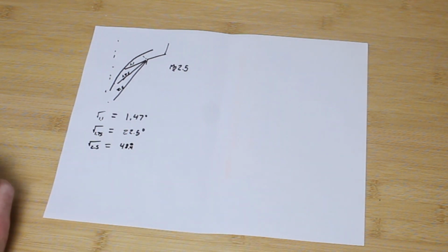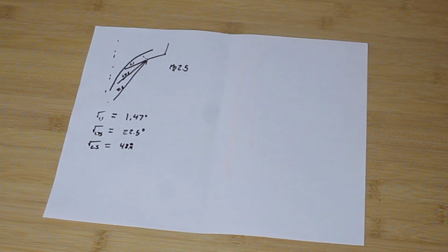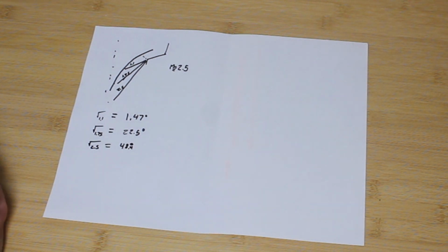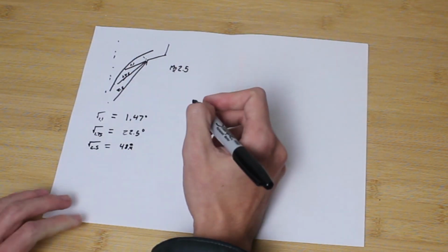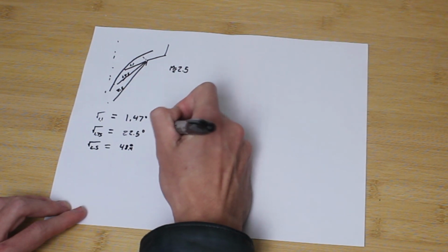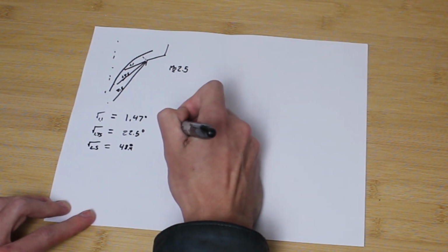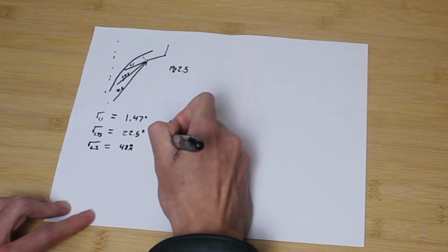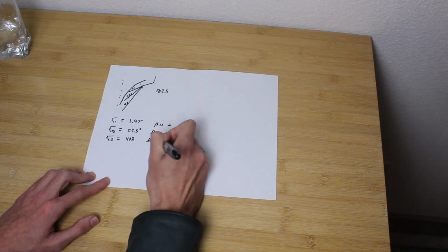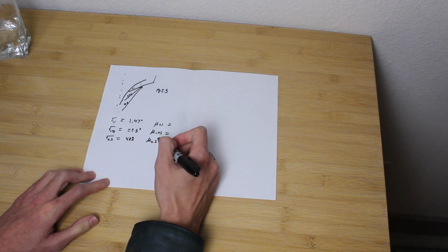So now that we've got that, those are the Prandtl-Meyer angles along each of those Mach lines. Now we need to solve for the Mach angle at each of those positions. That's going to be relatively straightforward. It's represented by this mu character, and we'll have that once again for 1.1, 1.75, and 2.5. Alright, so just real quick, what does Mach angle represent?